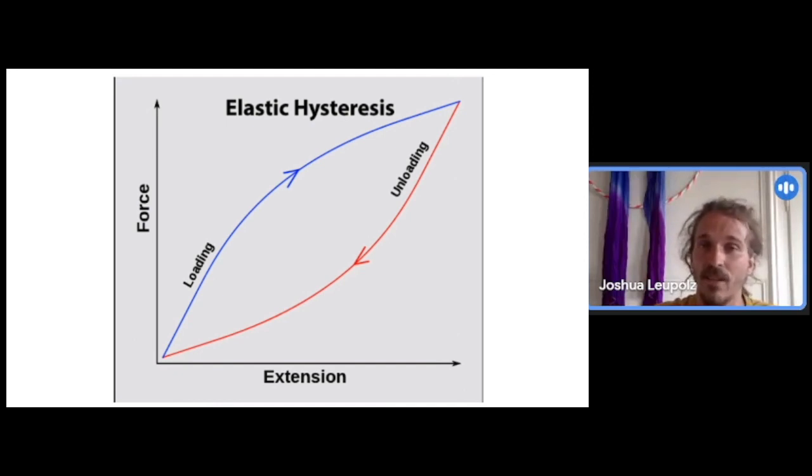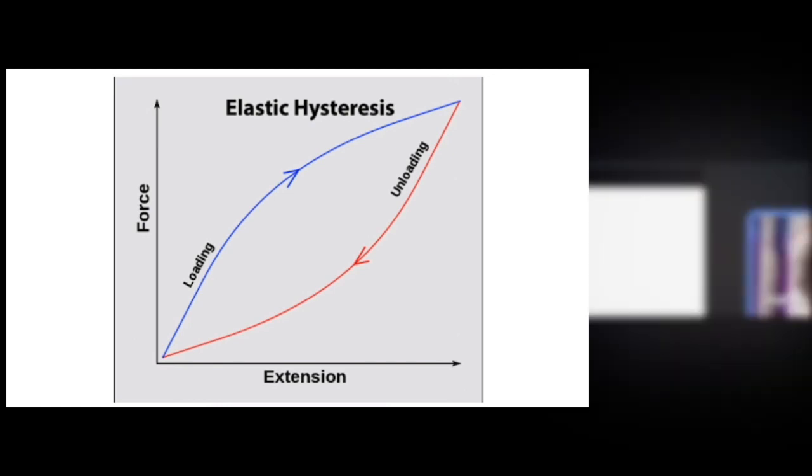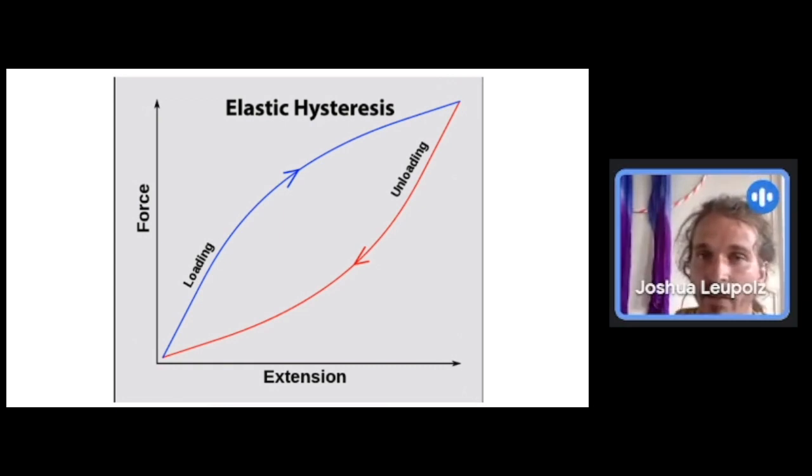But then, what Lorenzo was talking about, the dampening, you can actually see if you have this curve with the blue and the red line, so going up the tension and going down the tension. If you have this picture of it, you can see how much area is between these 2 curves, and therefore you can estimate how much is the dampening effect, so how much loss is happening when bouncing. I think that can be pretty interesting to see, and then you maybe can also measure this graphically, measure the area and give it a number.